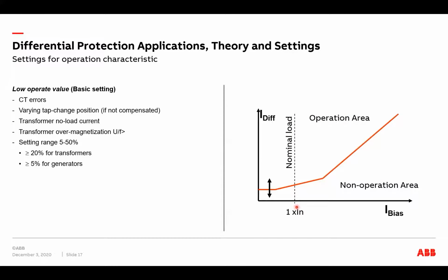Looking then at the different settings for the stabilized differential stage. The first setting we have here is the low operate value. When defining the setting for the low operate value, we should consider CT errors and varying tap changer position.